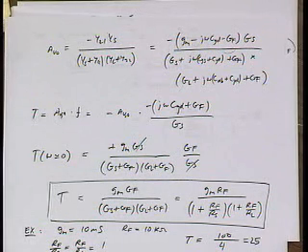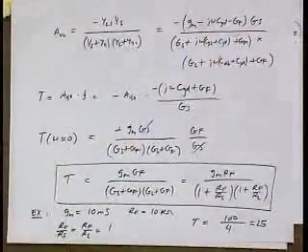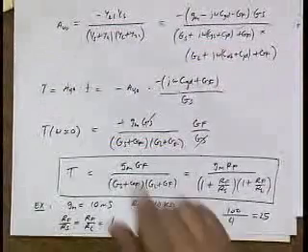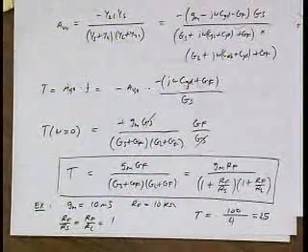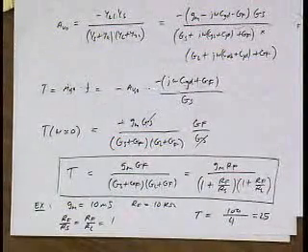Oh yeah, Christian. Because the amplifier is inverting, so any signal that feeds through will be positive, whereas its amplified version will be negative. That's exactly right. Remember, we have an inverting amplifier, right? But the feed-forward just sends the signal and doesn't flip its sign to the output. So these are actually two competing things.